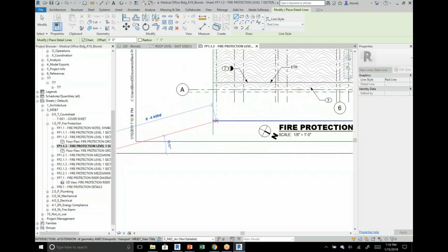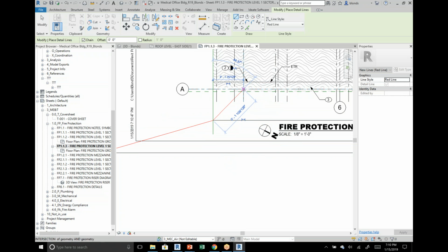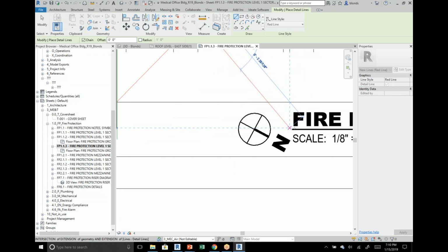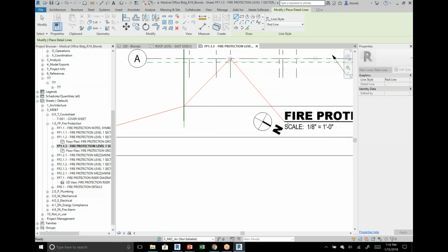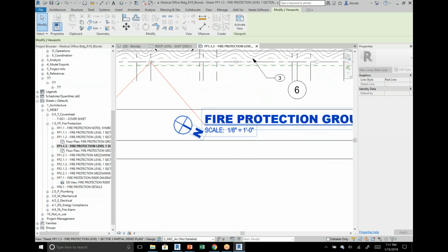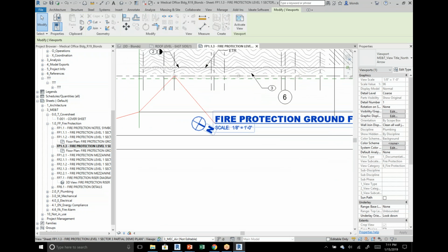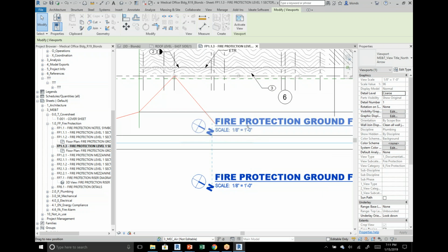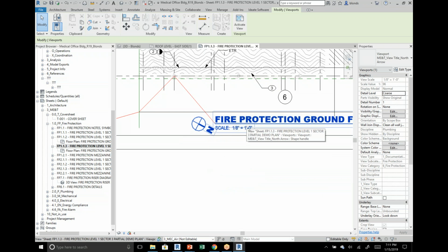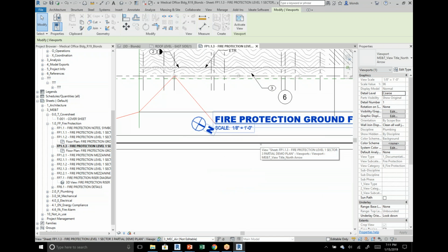So I'm just going to grab, let's say, the corner, this grid line over here, make sure I'm grabbing the intersection, and grab that point. And I'm also going to come right over here, and say, you know what, it doesn't truly connect to it, but this is going to give me a better chance to adjust my view title and have consistent placement. So as I place it on the next view, I'll know, okay, I'm just going to drag this to that same point more or less. That might not be as perfectly positioned, but it'll at least be very close.